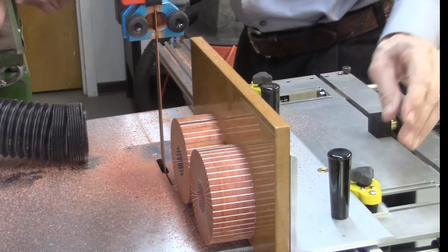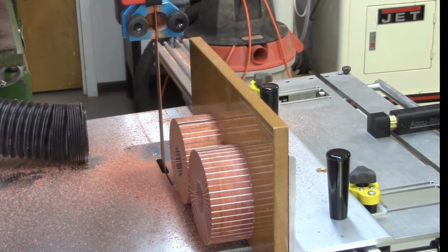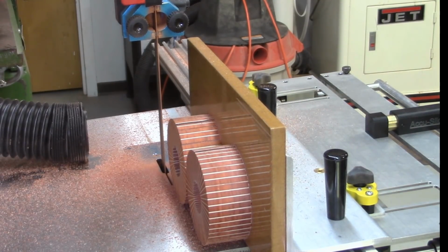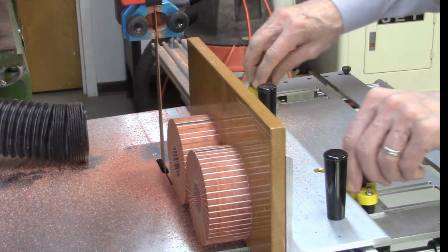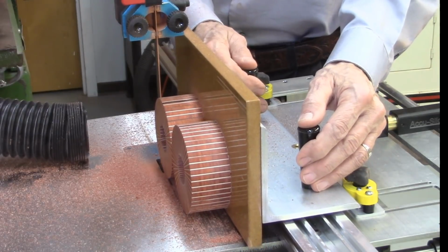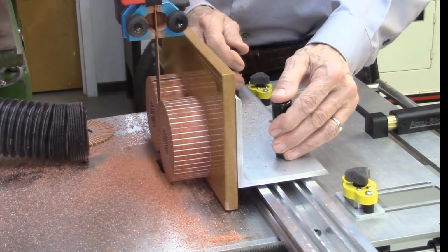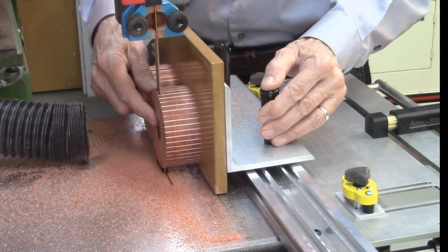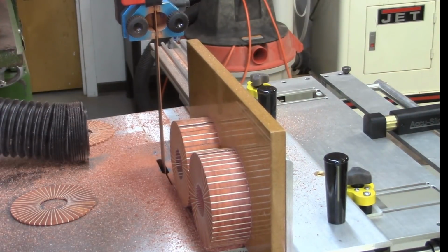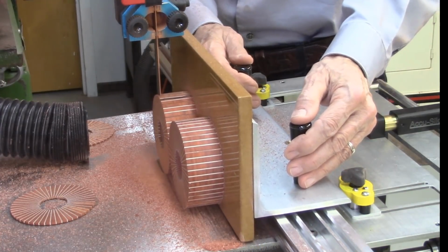After this first cut, the mag jig clamps are released and the discs are moved back to the starting point. The index wheels advance 1 full turn to allow for the bandsaw blade curve, and then advance 2 more full turns, or 0.100 inches, to provide for desired disc thickness as required for this project. The mag jigs are activated and the disc slices are cut. This slicing of the disc is continued until all the required segment discs have been cut.